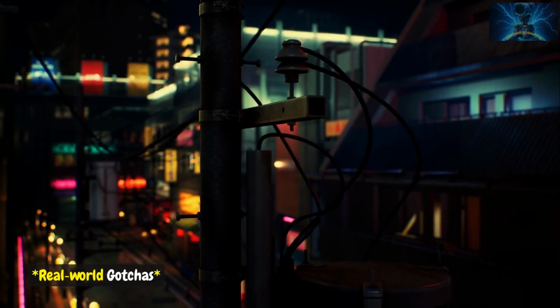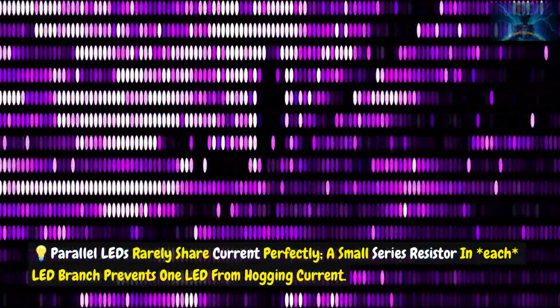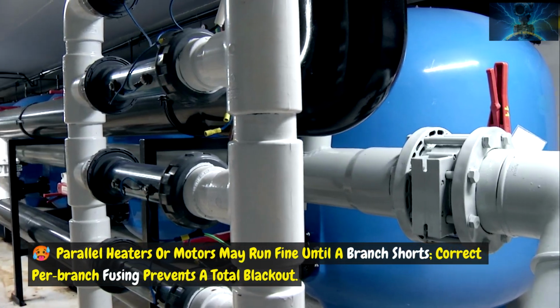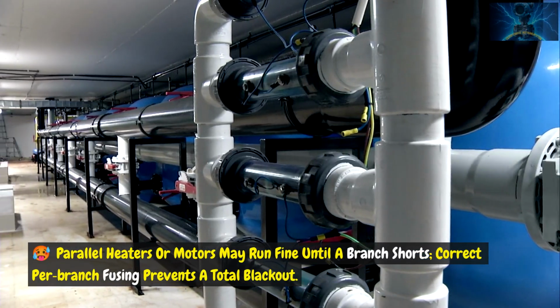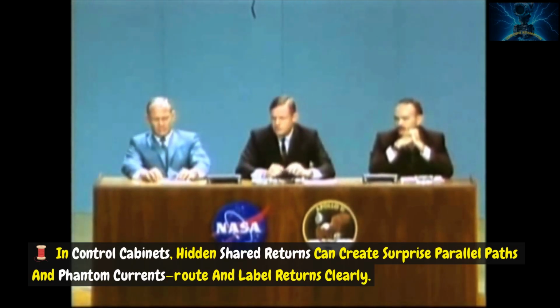Real-world gotchas. Parallel LEDs rarely share current perfectly. A small series resistor in each LED branch prevents one LED from hogging current. Parallel heaters or motors may run fine until a branch shorts. Correct per-branch fusing prevents a total blackout. In control cabinets, hidden shared returns can create surprise parallel paths and phantom currents. Route and label returns clearly.